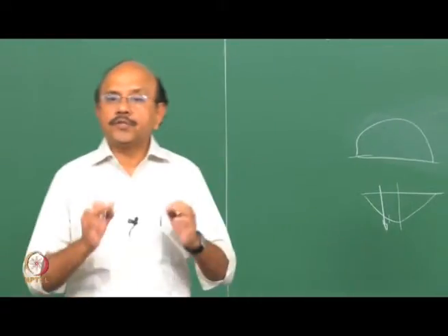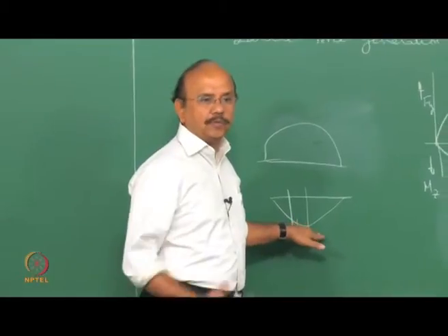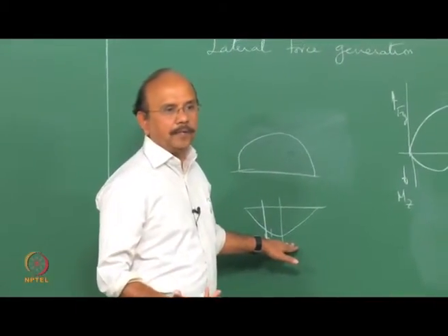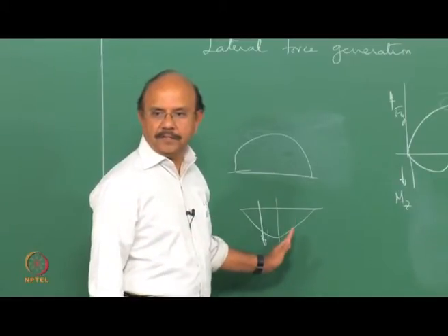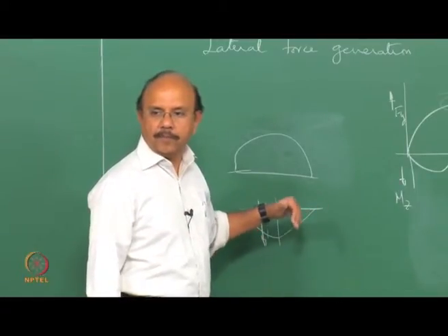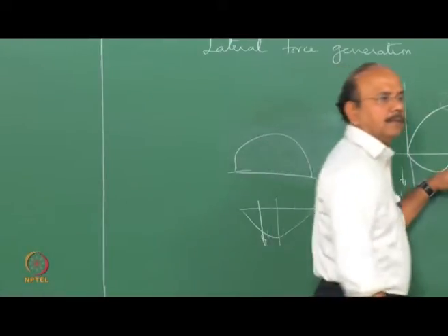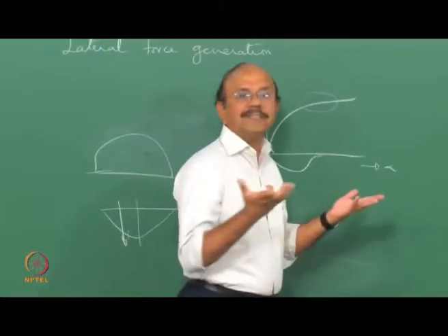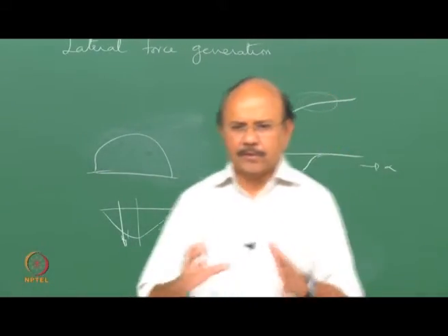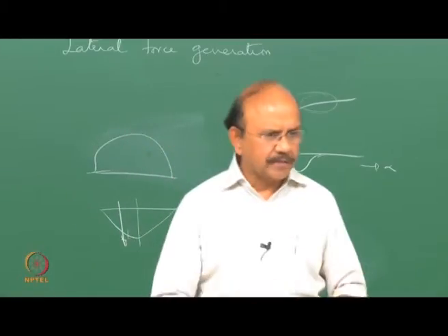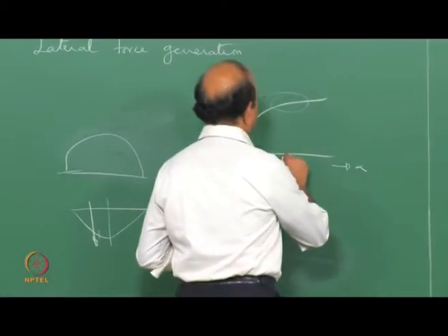So if you assume, for example, a good parabolic distribution, the mu qz also will be parabolic, and hence it will be exactly symmetric, with the force sitting at the center. So for a brush model with a parabolic pressure distribution, the aligning torque goes to 0. Actually, it doesn't go exactly to 0 because it's not very symmetric, and hence it may be something like this, and so on.